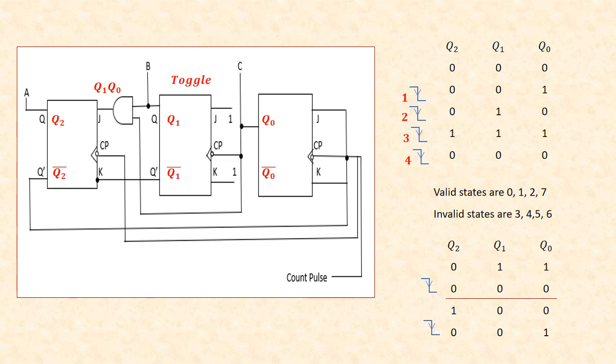During the first negative transition, our Q0 will be 0 because its input is J equal to K equal to 1, which is nothing but Q2 bar. So the first flip-flop output Q0 will change from 1 to 0, and similarly the second flip-flop Q1 also changes from 1 to 0, because a negative edge transition is given as clock pulse to this flip-flop.